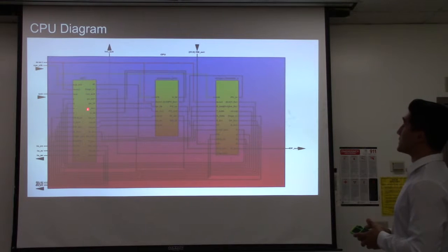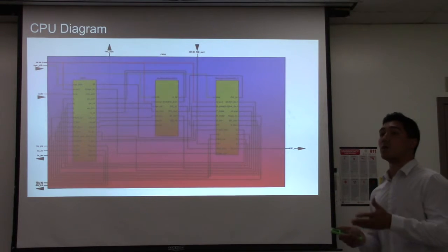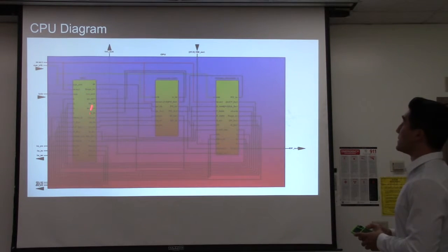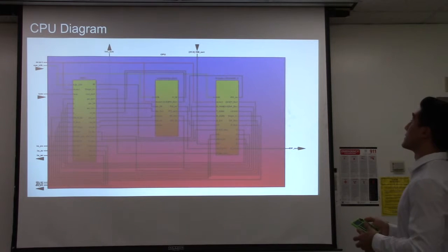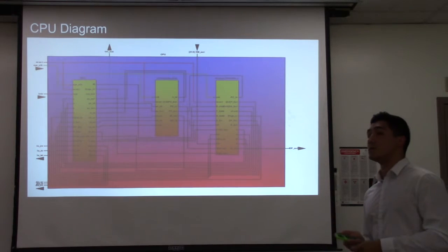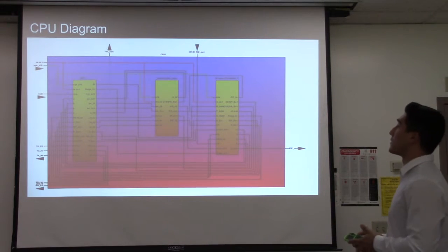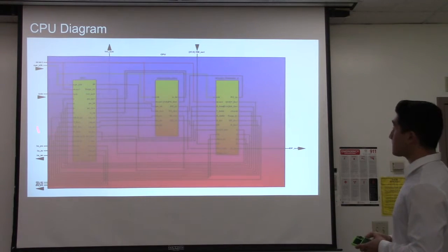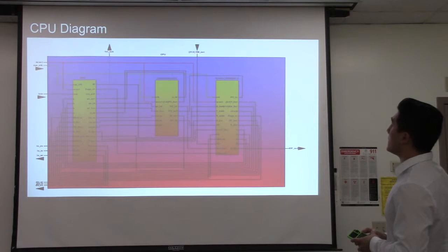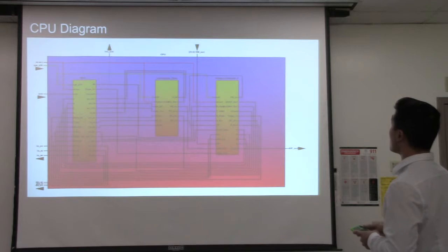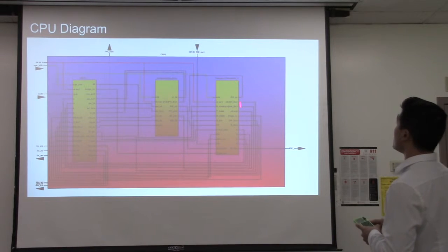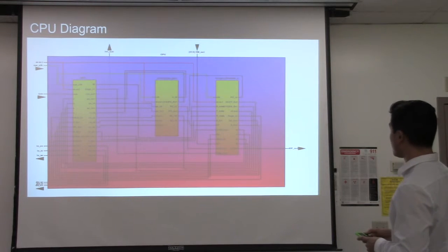And most of our instructions are going to have a regular PC increment, which increments the PC by 4. Otherwise, we have a PC load or a PC select to select other values to be inputted into PC or added onto PC for a jump or other instructions. We're going to keep going and look more in depth into the integer data path now.